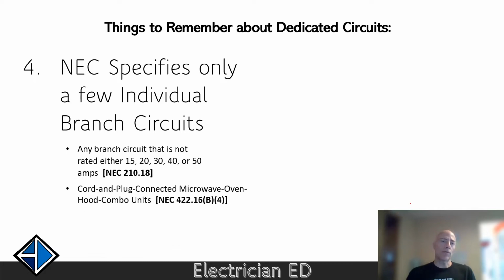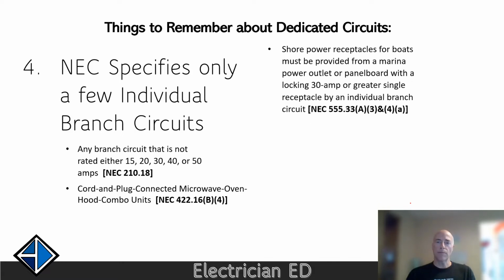Also, if you have a cord and plug microwave oven hood combo unit, or I think even just an oven hood, it needs an individual branch circuit. And then, now, not everybody is going to have a boat dock, but if you have a receptacle that's designed for shore power to a boat, you come up, you dock your boat, you plug into your shore power.